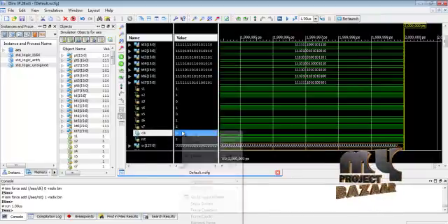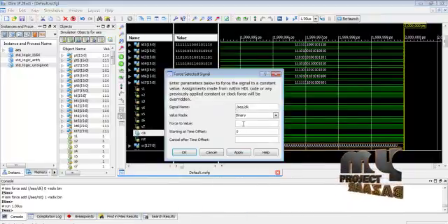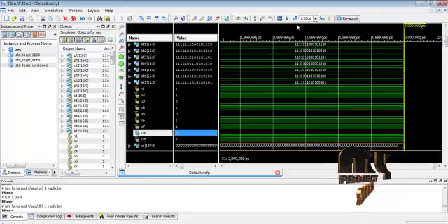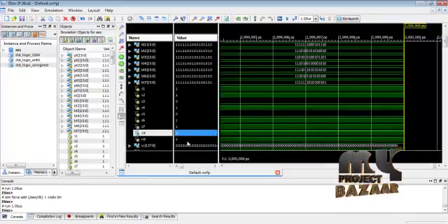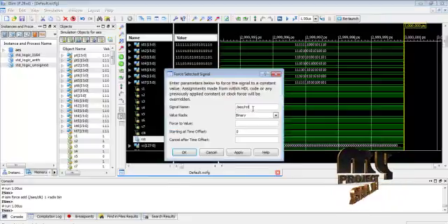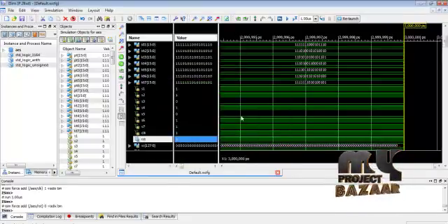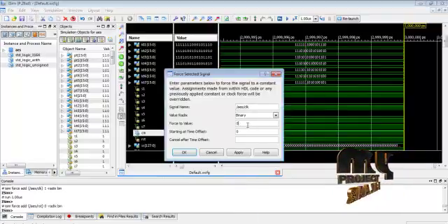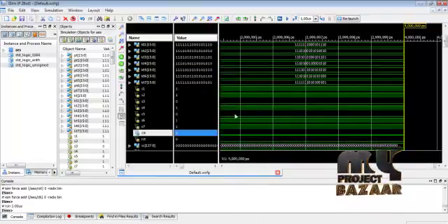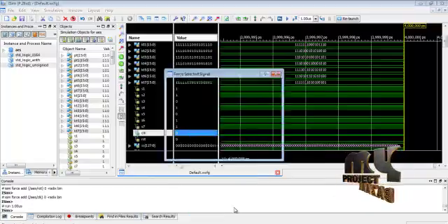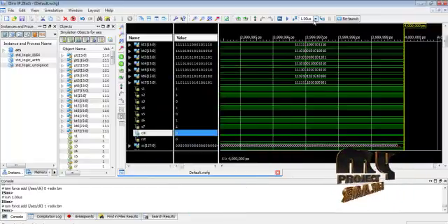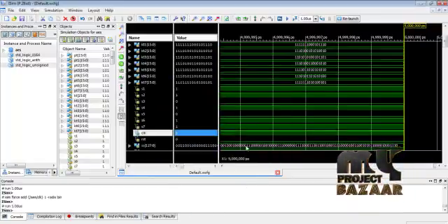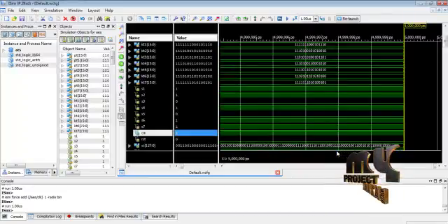Then activate the clocking signal, but the reset function is 0, so all of the outputs are 0. Then deactivate the reset function and apply the clocking signal. Then we create the final output result for the 128-bit results of the AES architecture.